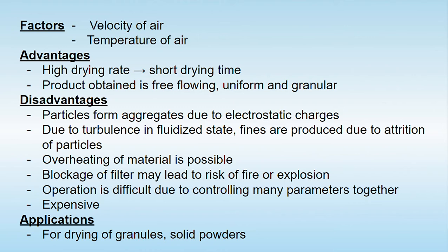Yes, this fluidized bed dryer is very widely used because of two advantages. Yes, it has a higher drying rate, so the drying time or the entire drying cycle will be very short. Yes, the product obtained is very free flowing because the individual particles are going to dry in contact with the hot air. So the product is free flowing and uniform, with a granular nature.